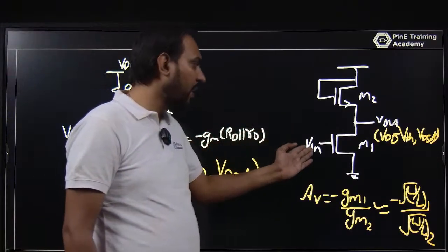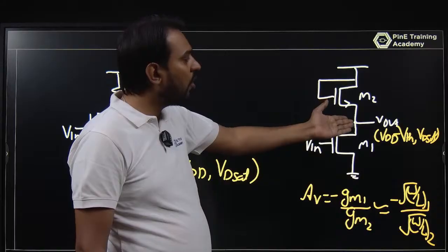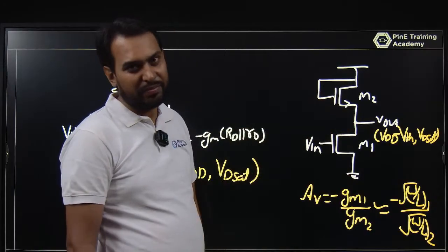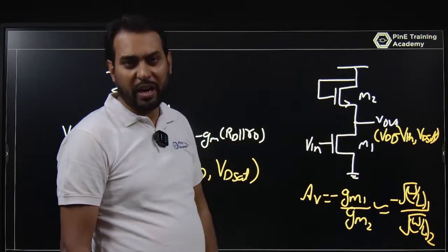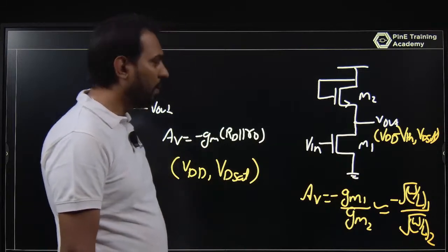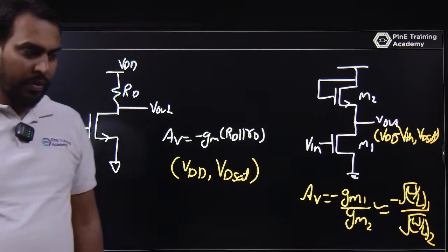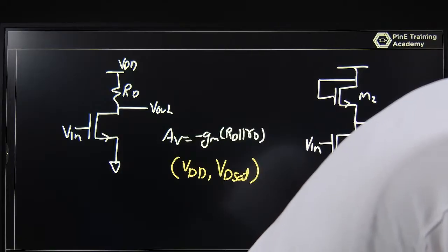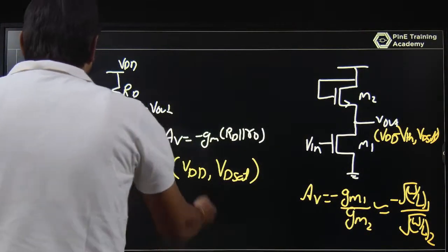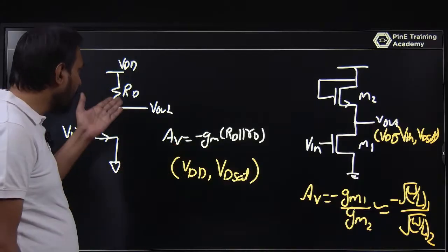Similarly here, if you are providing the input as 0, this MOSFET is not on, there is no current, so Vout reaches what? It is VDD minus VTH, the maximum voltage. If input is high, then it will go towards the ground. So it behaves not like a buffer, it acts like an inverter here. The common source amplifier acts like an inverter. Okay. That is a low swing, or rather not a low swing, comparatively it is less swing. It is a small swing compared to that resistive load.